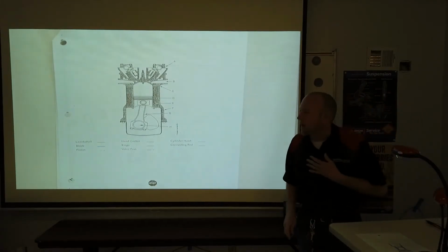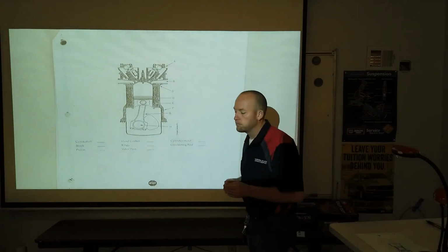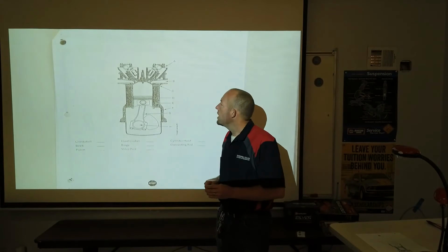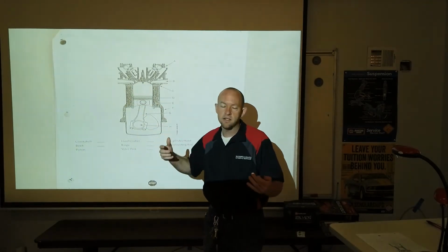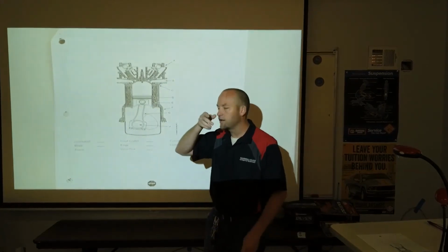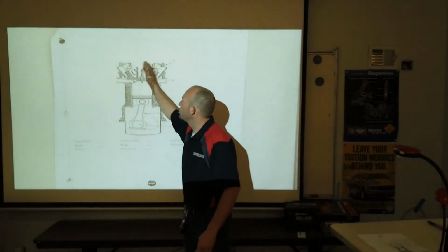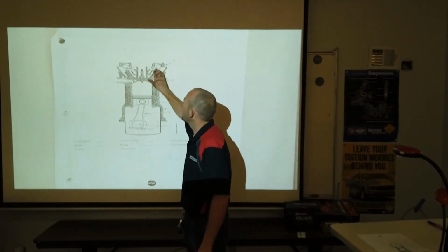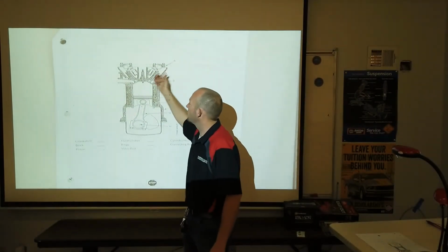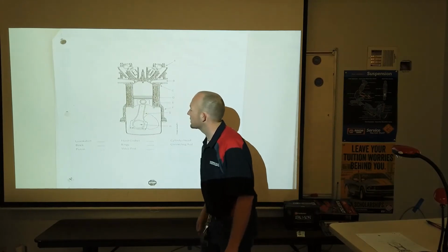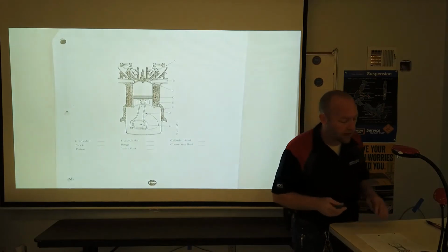So next I want to talk about some of the names of the parts that we'll use for an internal combustion engine, to get some of the vocabulary down. The design that you see up here looks like what we would call a hemispherical design, but this is a modern combustion chamber design that is referred to as a pentroof design. This would be a dual overhead cam motor where we can see that we've got our cam lobes here on either side, one for our intake and one for the exhaust. So we'll go ahead and look at the main components and names that we have here.